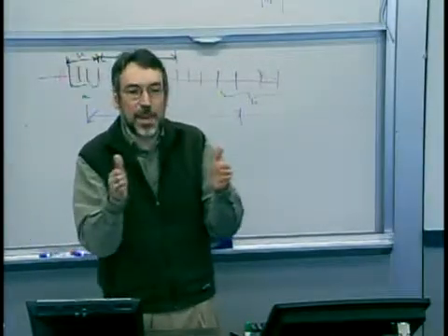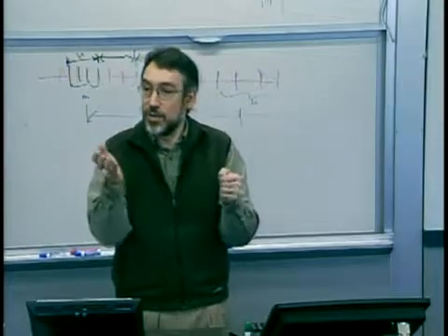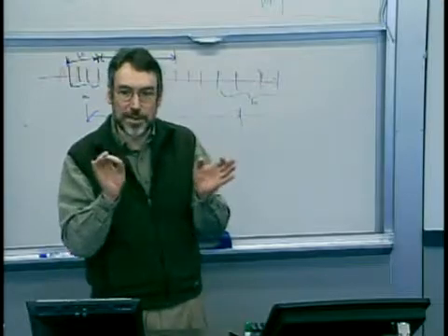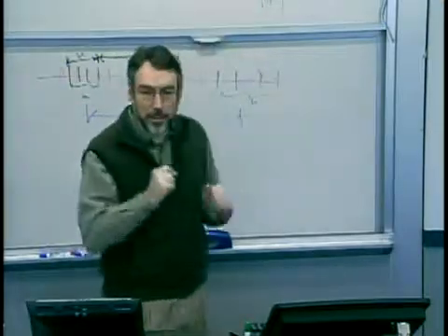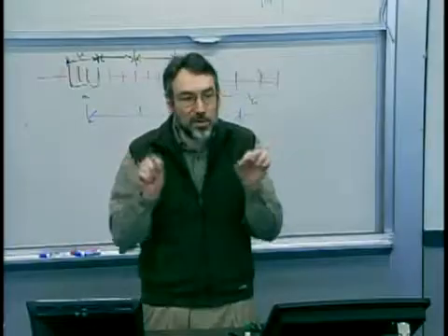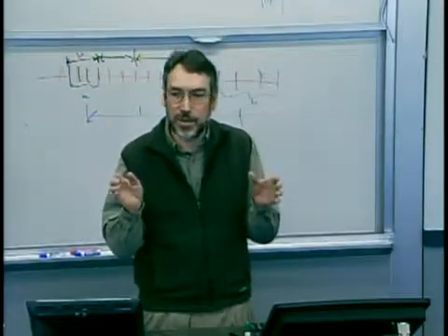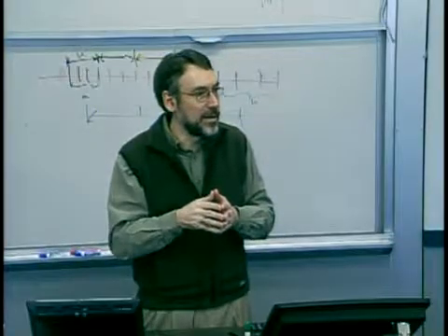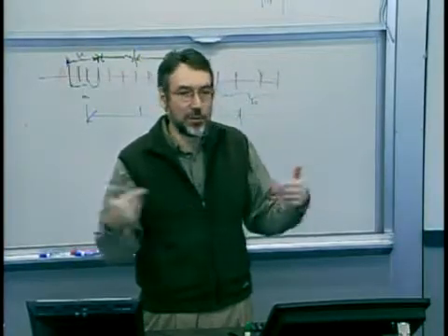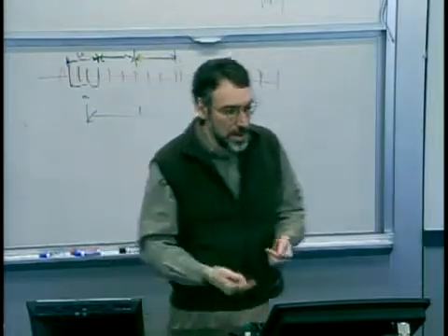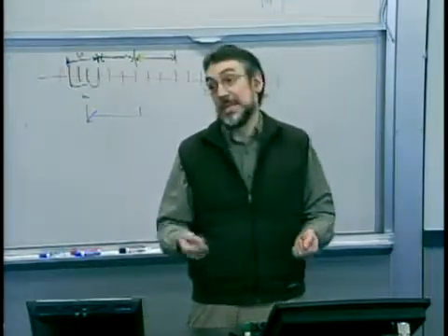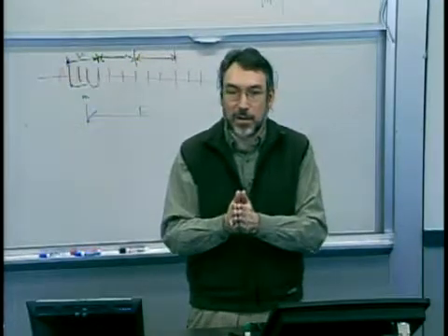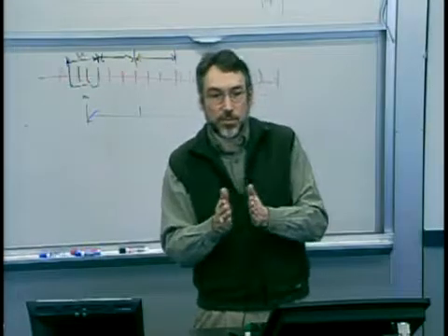If I tightened up my spec limits, if you just know CP and CPK, you can back out, because that's all in terms of normalized standard deviations, the probabilities associated with the number of parts that are not going to conform to those specifications. So if I purely tell you CP and CPK, you know probabilities, fractions of non-conforming parts. Okay? And then you can start to compare how much it would buy me to move my mean, in terms of fraction of non-conforming parts. How much would it buy me?